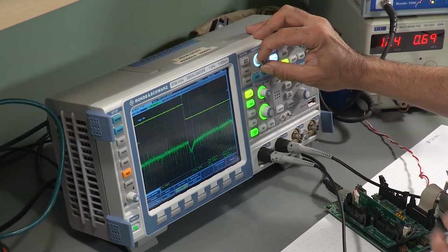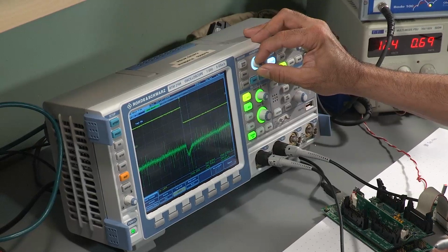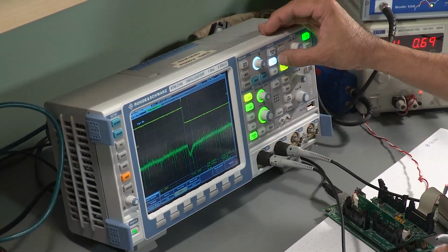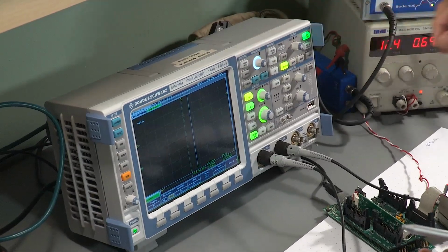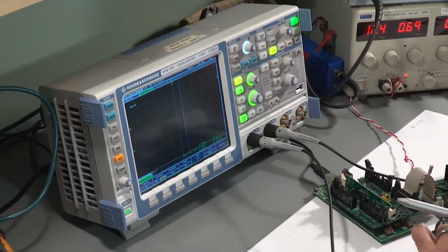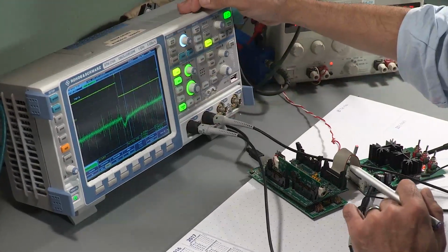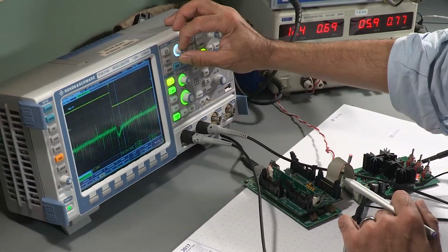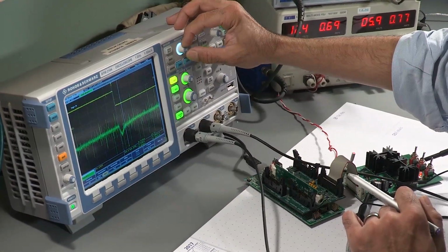The settling time at the moment is measuring around 75 microseconds with no ringing, and I can also use the cursors to measure by hand if I don't want to use that. So if I again do another trigger, with my cursors I've got around 75 microseconds,